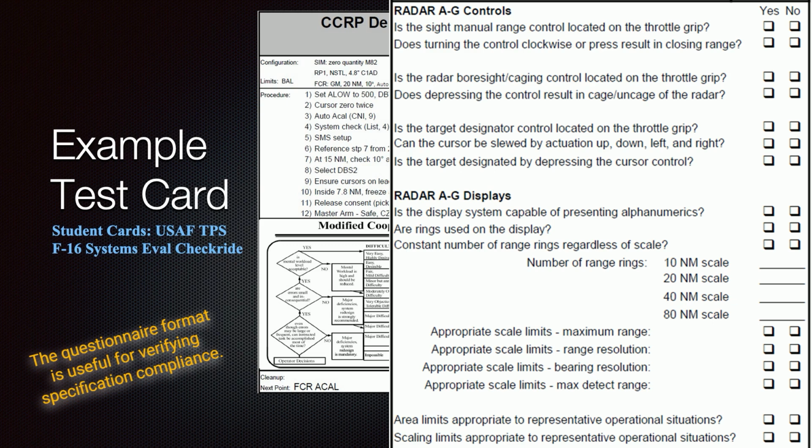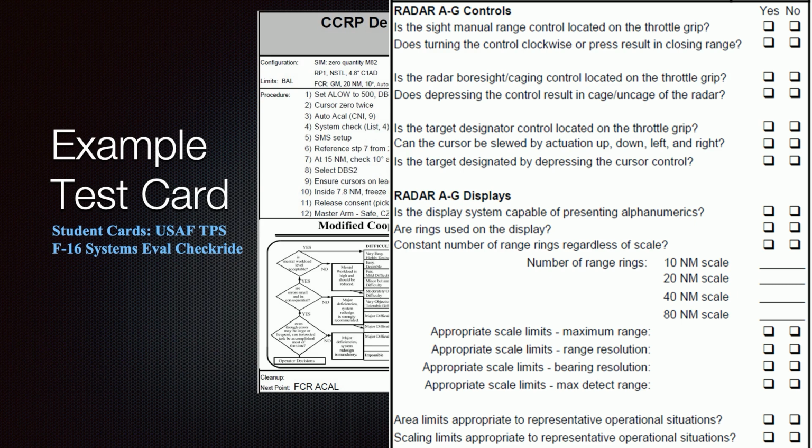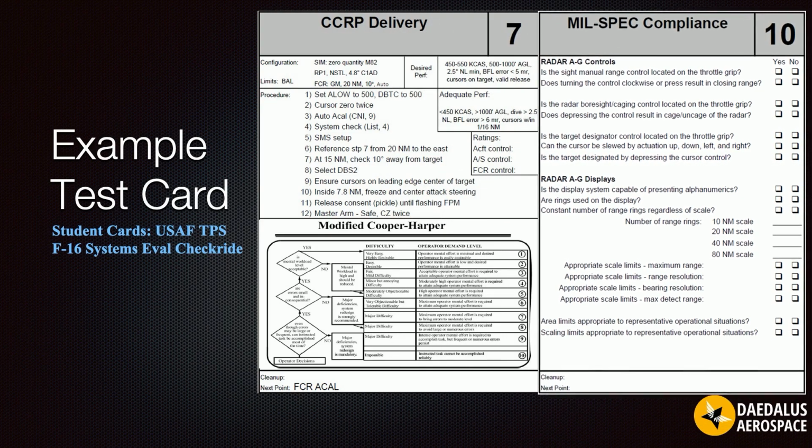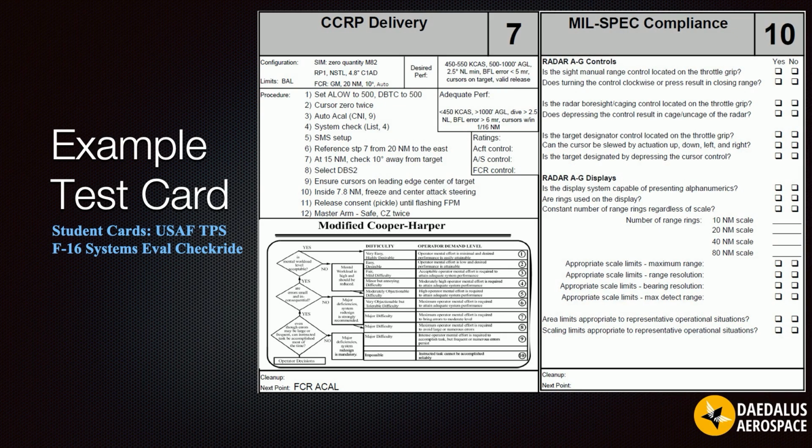While this sort of questionnaire could be completed after the flight, it's usually best for data fidelity to get the answers in flight immediately after having flown the test. Burning a little bit of extra fuel while you're running this sort of card is worth the expense because it will also serve to capture pilot comments that can often be the best data for validating or refining a system design. So what essential elements of test cards do you notice included with this example? Any elements missing?